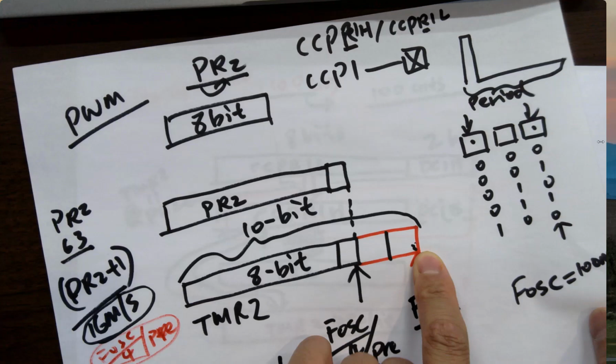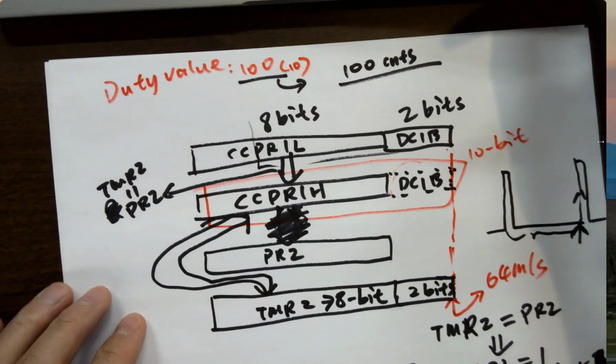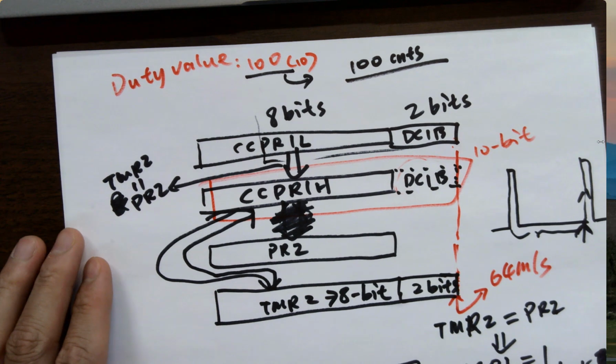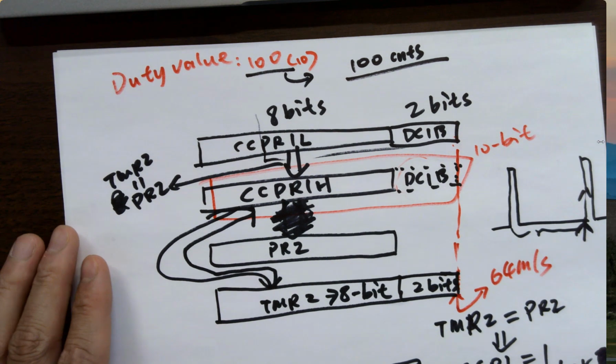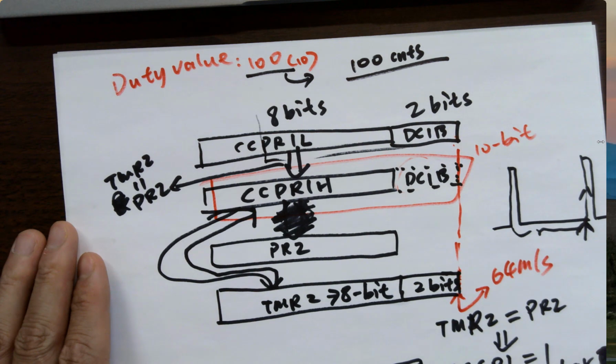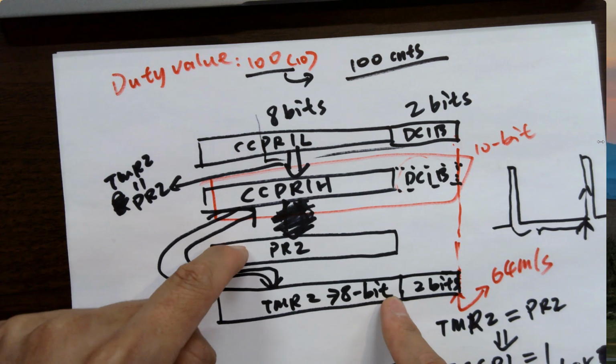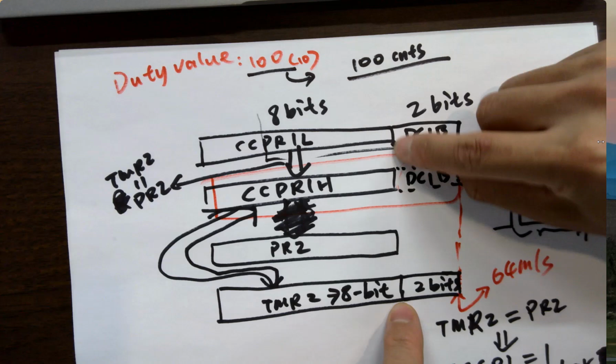Does that make sense? I've got a question. Can you go to the other page real quick? So over here we're comparing, because I understand that FOSC is the rate at which the least significant bit is toggling, right? Yeah. But the part of the timer that we're reading from is the third bit that's toggling at FOSC over 4. So if that's the bit that we're reading from, that's what's being compared to CCPR1L. No. Oh, yes. Because these two are aligned as well.